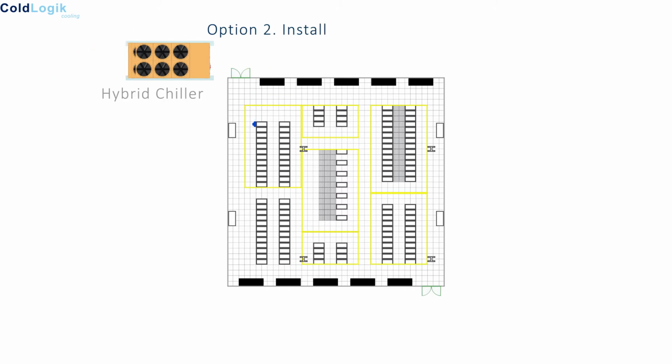With option 2, not only do you have the ability to deploy higher density racks in the data hall, one of the main benefits of installing new external cooling plant is the ability to reduce energy consumption over traditional cooling methods. As a direct comparison to traditional perimeter cooling, up to 93% more energy can be saved. Once more, the supply water is above dew point, so no condensation trays or CDU are required.